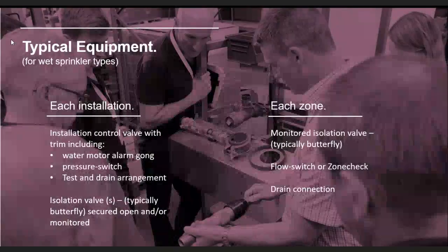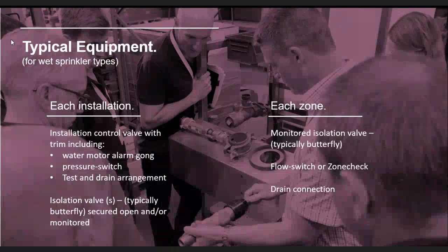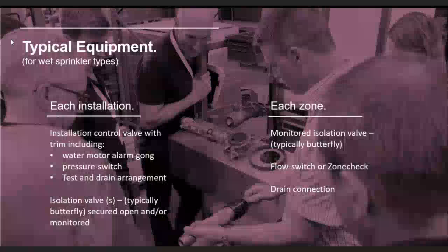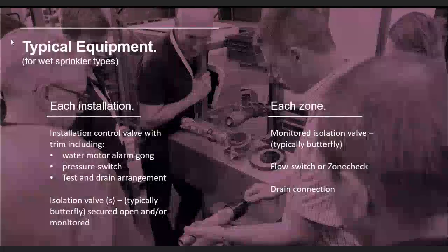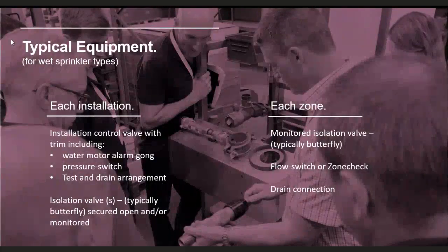Each zone has got a monitored isolation valve. The isolation valves on the installation might be monitored, they might not be. They might be just secured in the open position. This all depends really on whether it's life safety or not. For life safety, we have to monitor all the stop valves. If it's not life safety, then we have the option to. Often they will be monitored at the installation,